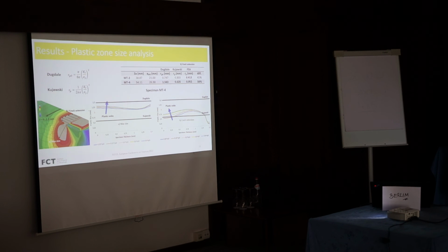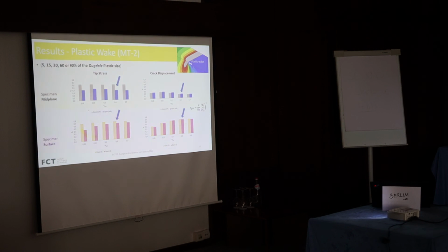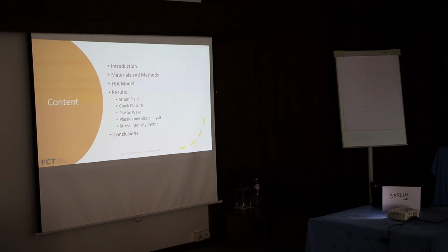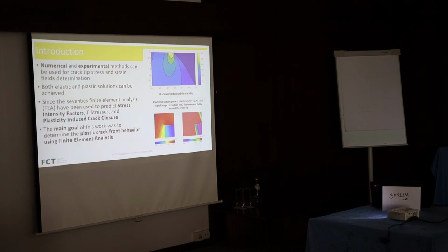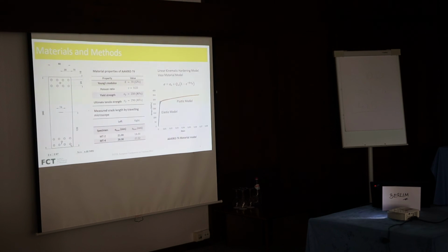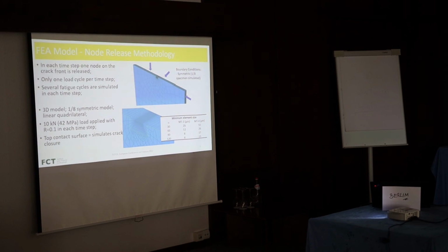So, if no other question, I have the specimen thickness. Maybe I missed the thickness. The thickness I can show you here, but it was 3 millimeters. Yes, 3 millimeters. Okay. And the load ratio in the simulation? 0.1. Okay, 0.1 stress ratio. We always apply 10 kilonewtons, the maximum load that was applied in the experimental tests, and for the simulations, 0.1.